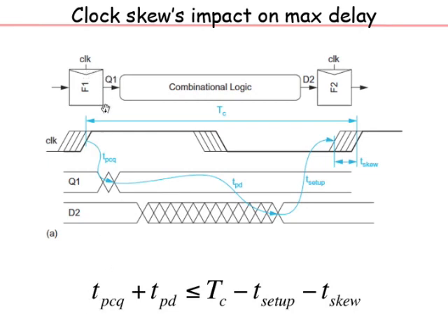I'm throwing out these numbers, 100 picoseconds. Of course, it depends on the process technology, right? The fan out 4 delay in, for example, a 14 nanometer process will be maybe about 5 picoseconds. So you can expect propagation delay clock to Q also of the order of a fan out 4 delay. Setup time also of the order of a fan out 4 delay, and perhaps a few fan out 4 delays. Again, it depends on how well you control. So in that case, of 1000 picoseconds, you lose maybe about 15-20 picoseconds for all these overheads.